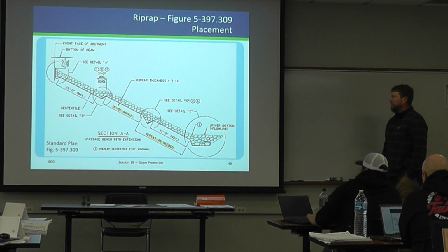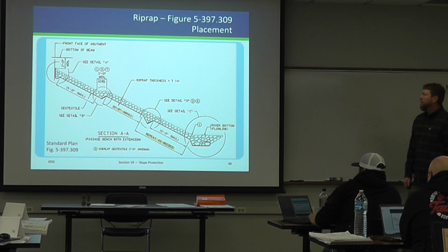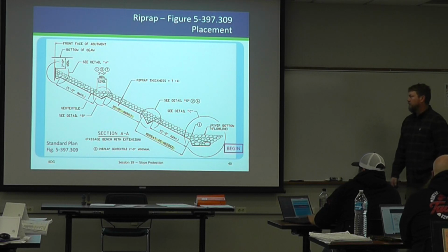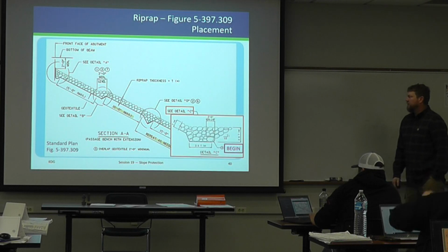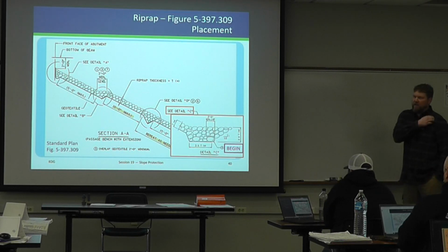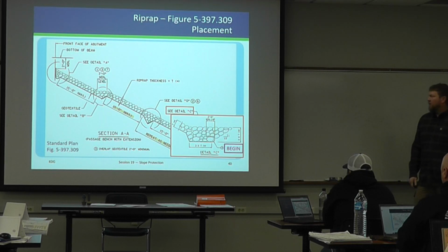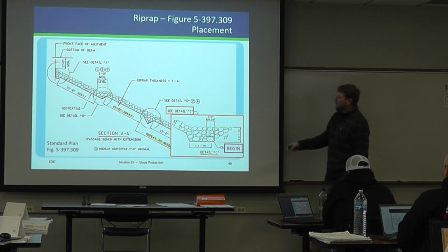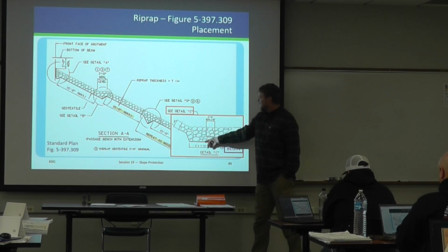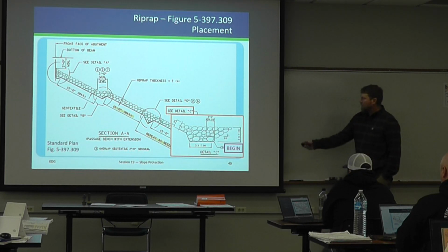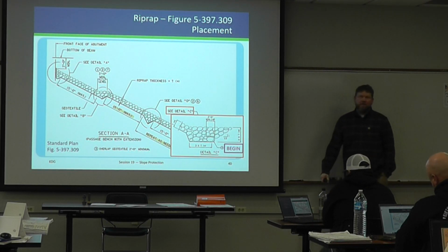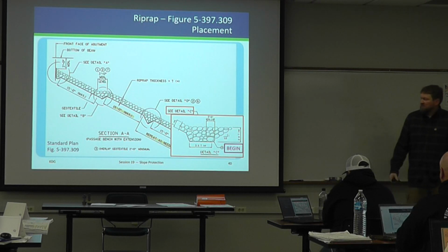Just a schematic, probably just common sense, plain obvious, but run through it anyway. So remember, we want to start at the bottom and work our way up. So this detail C is the toe-in at the bottom of the riprap slope in the river. Does anyone think we're going to get exactly that? No. What would you say? Do we notice that it's maybe a little thicker than the main slope itself? Yep. Trying to get maybe some wrapping of the fabric around the rock.